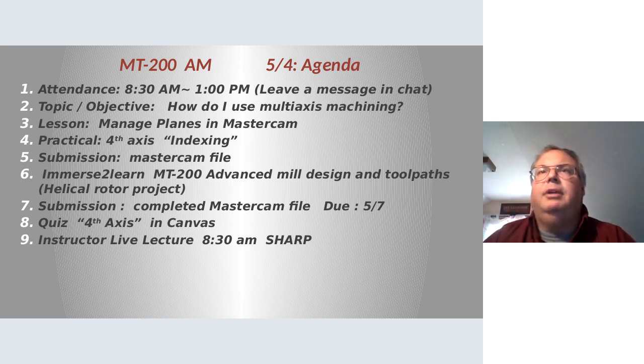All right, so you can go as far as simulating your work holding in Mastercam. You can simulate machine, tool holder. All right, the stick out length of the tools, the shank diameters of the tools, all of these different aspects to make verification the most accurate. All right, and the reason for that is, of course, to look for collisions or look for gouging or any kind of problems you would have when you actually start to run these parts. All right, so that's a valuable part of Mastercam, is the verification and the ability to prove these things out.